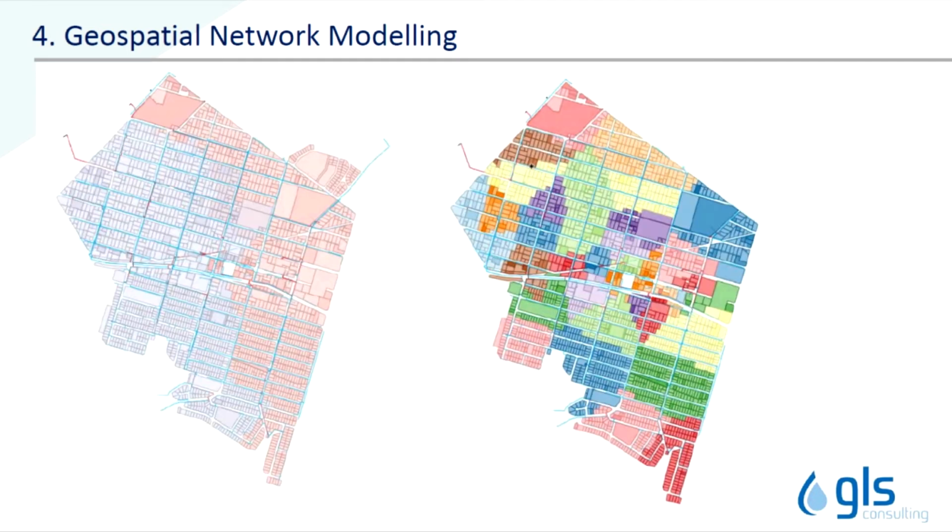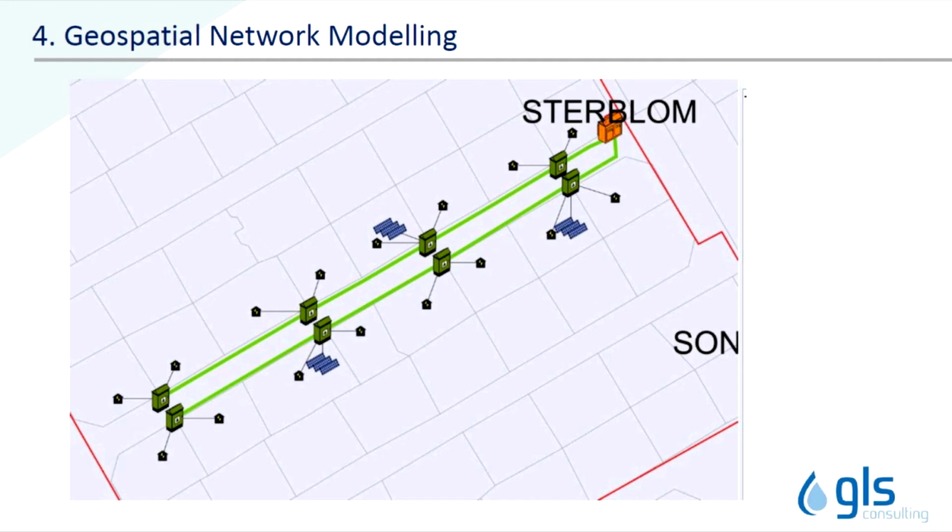On the next slide, you'll see on the left the two different colors represent stands fed by two different substations in that particular area. On the right is the same network, where every stand is now colored according to the particular MV-LV transformer or mini sub that they are supplied from. This is just to give you a visual feel for the useful functionality that you gain from this feature and the visibility that you gain into your network. This shows that we can go all the way up to the low voltage network. We can model on a per stand basis, and you can also model distributed generation.